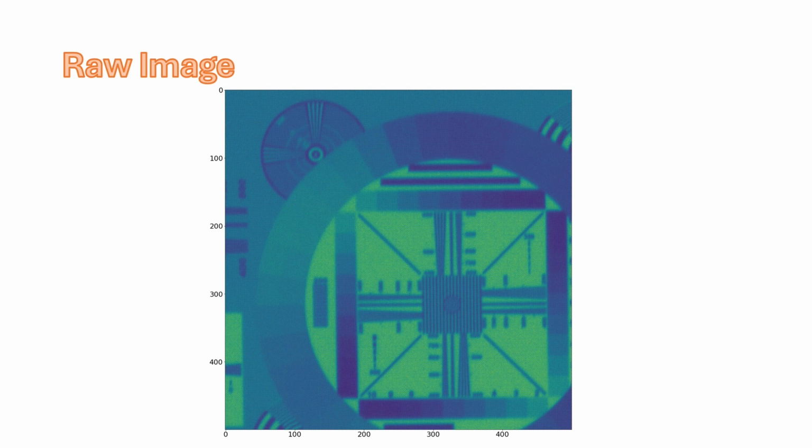Samsung allows you to capture raw images, which is interesting, of course, when you have 100 and 200 megapixel images, because it's not really the raw sensor data in that case. There's necessarily some processing. So increasingly, for sensors that are oversampling with very large pixel counts, what they deliver as a raw image has already been processed in some way. But where we have these 12 megapixel sensors, you can capture the raw Bayer data.